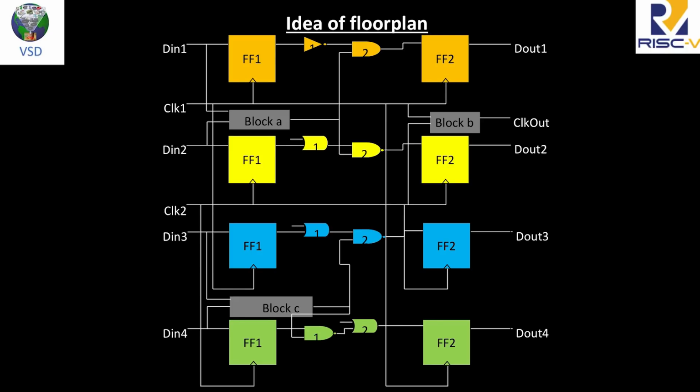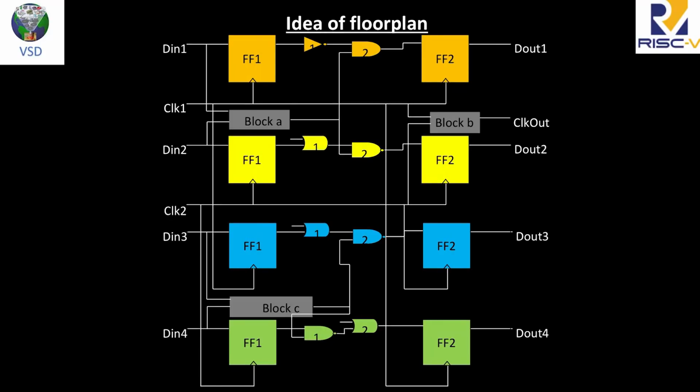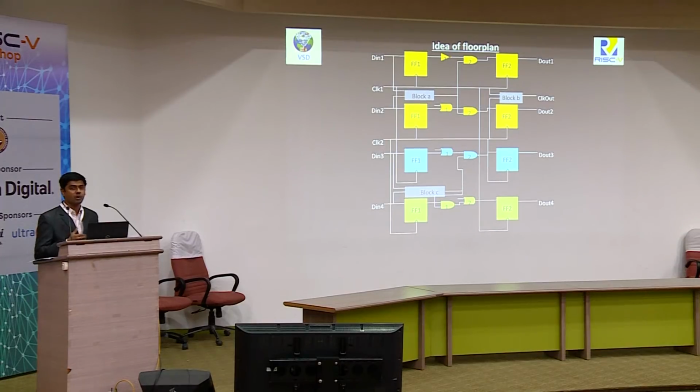The thing that we're trying to propose, or what we surveyed over here, was about the floor planning of a chip. We took an E31 RISC-V core, which after post synthesis was about a 112,000 instance count design. But before even getting to the synthesis level, just when we get the RTL level, we did analysis on that particular design to make it compact and to make it high performance. So this is basically a survey of that. And while doing the entire survey, the entire analysis, we always use open source EDA tools, and that's what this is about.